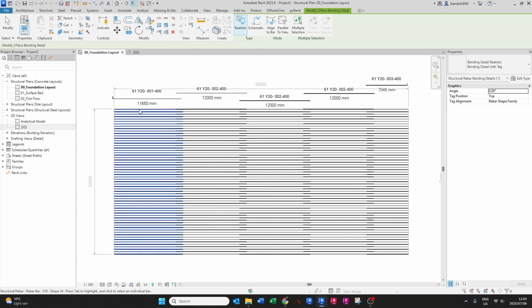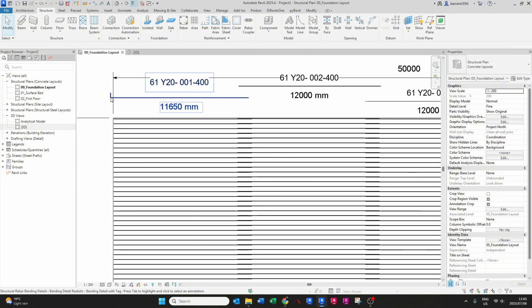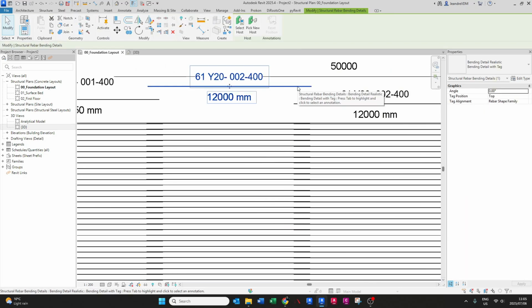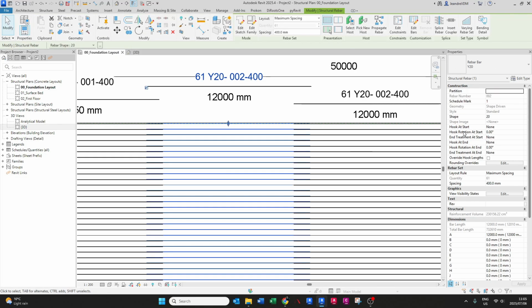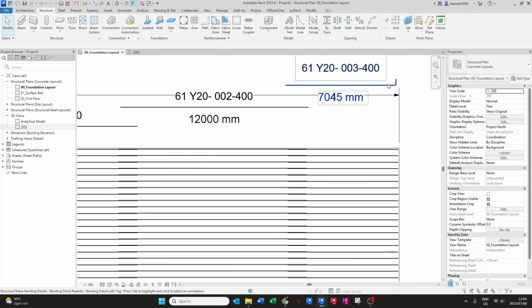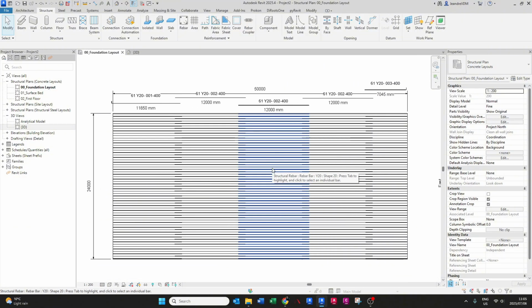And you can also see what Revit does for you is, because we've placed our reinforcement in the beginning as a shapecode which has hooks on the end, it leaves that hook for us here, and internally it just creates a shapecode 20 for us. So this is the South African standard. A shapecode 20 is just a straight bar, which then it creates for us, and then here on this edge again it keeps that bar for us with the hook on. So this is a very useful tool.